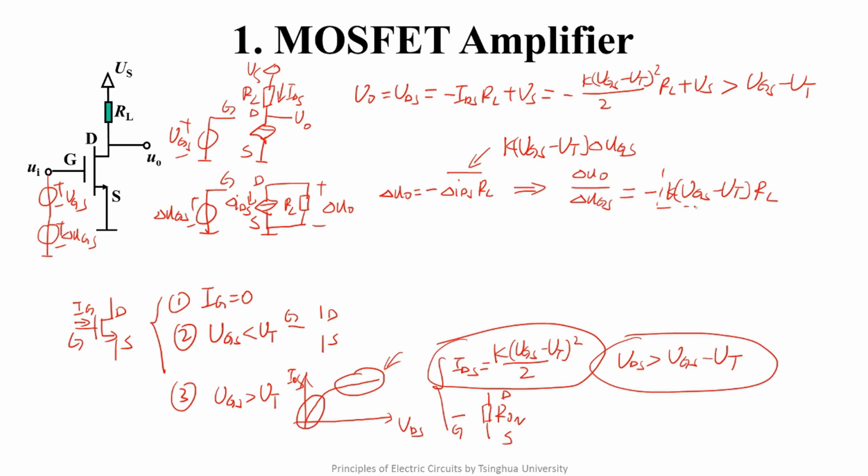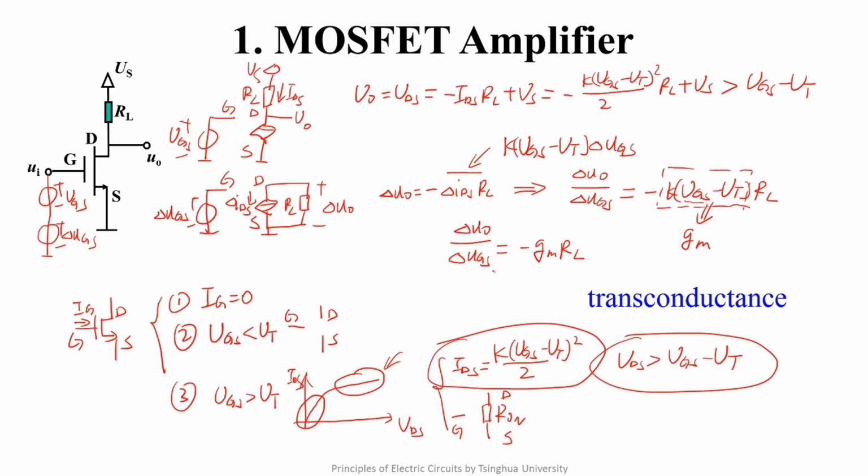Usually, the coefficient, which is determined by DC working point, is defined as a transconductance Gm. So the amplification of MOSFET amplifier can also be simplified as: if the excitation and response are sine signals, we can represent them by phasor with dots.